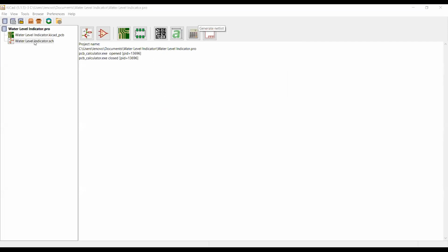This is the netlist. I told you, DRC will check the exact location and exact position of the components and the connection with the pads and the traces. And the netlist is that text file which will contain all the positions of those components and the traces.